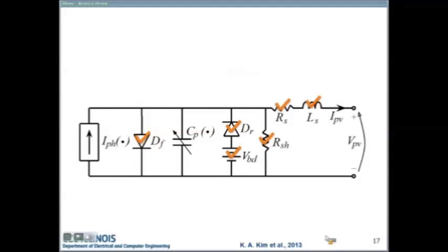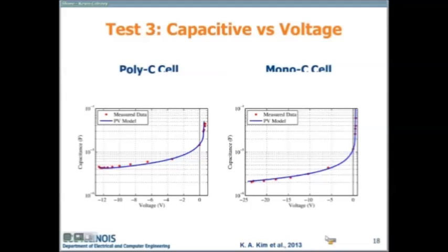So the last one that we have is the capacitance, which took a long time to really get. But luckily it comes out pretty nicely. So you have to calculate this out, but I'm just going to show you the results. Once you do all the right calculations, you can get the capacitance out as you vary the voltage. And so we see that this area is the junction capacitance. This is the diffusion capacitance area. And you can kind of see it here. If we had gone a little bit farther without overheating the element, that's one of the difficulties, we would actually see it start to go up a little bit more here. So that's the avalanche capacitance that a lot of people don't incorporate.